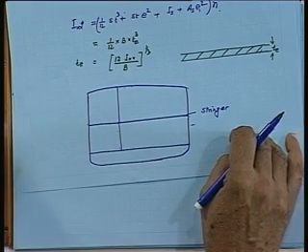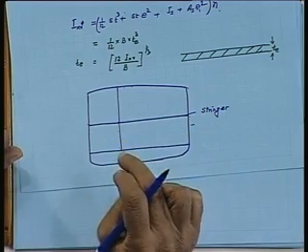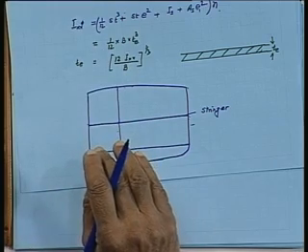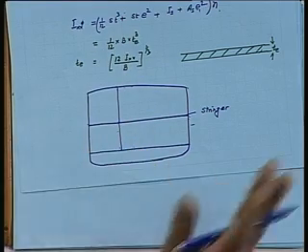In fact, in the majority of tankers they try to do this. The only thing is that if you are going to put a stringer, it will be a deep stringer, and it will try to occupy useful volume in the case of ordinary vessels. But in the case of a tanker, the liquid has to be filled in, so there is no problem. So, you can have a ring sort of a thing. In fact, in the tanker structure you have a stringer in the shell also. So, you can provide this here to cut the span.